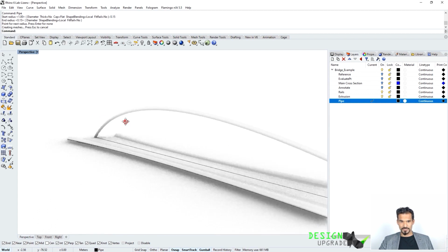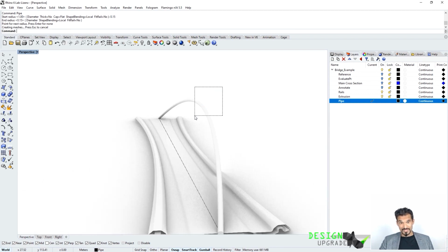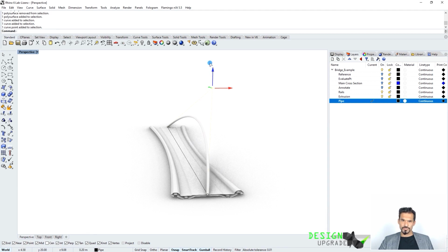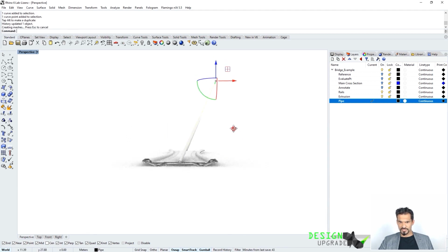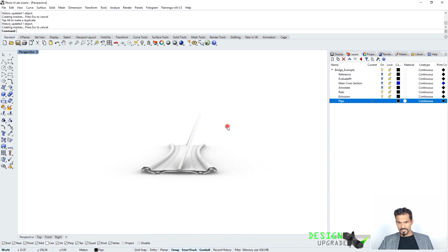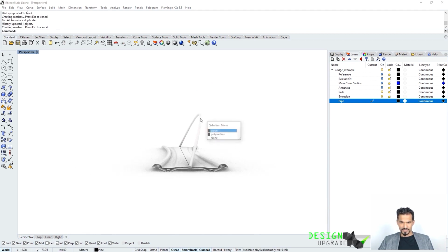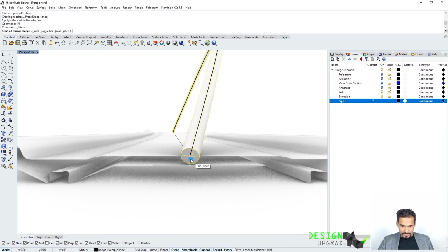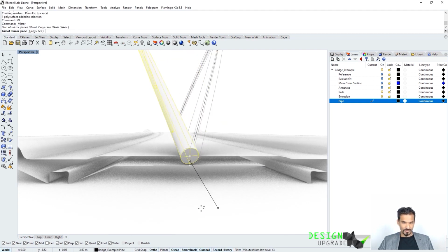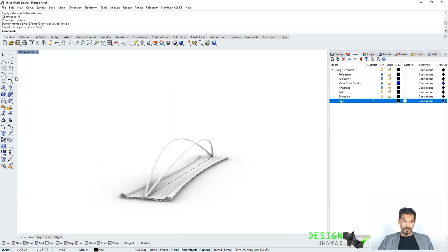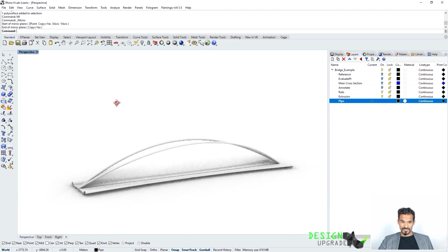That's a bit steep, but the nice thing about this is we can just select our initial curve, take that point and move it up. If we feel that this is too steep, this looks a bit better, we can also put it up, etc. So you can just play with that, and we can then again do our record history, take that pipe and say mirror along the central axis. Just make sure, shift key, Y. Well, there you go. Now we already have our context there.